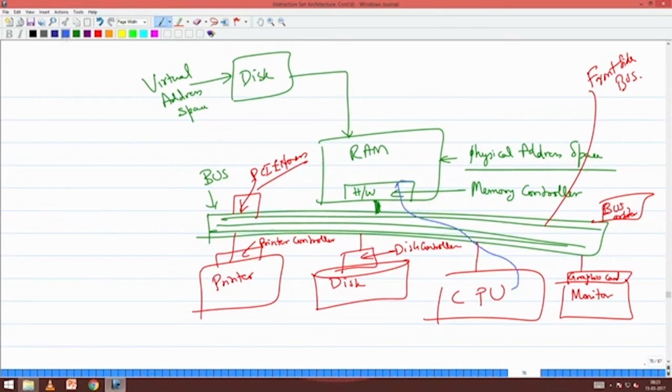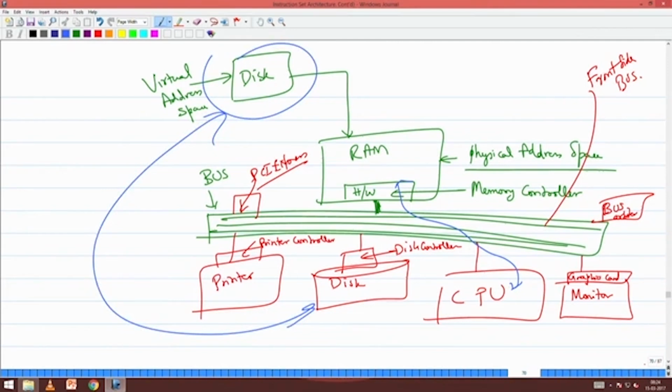Right? It accesses RAM, and whenever it has to go through this bus, it will wait. Essentially it waits to get that bus, so there is a latency tau, plus then there is a memory access time. Memory access is read or write, so I will call it the memory access time m. Suppose this tau plus m is the total time required for reading 1 byte from the memory. So tau is the latency.